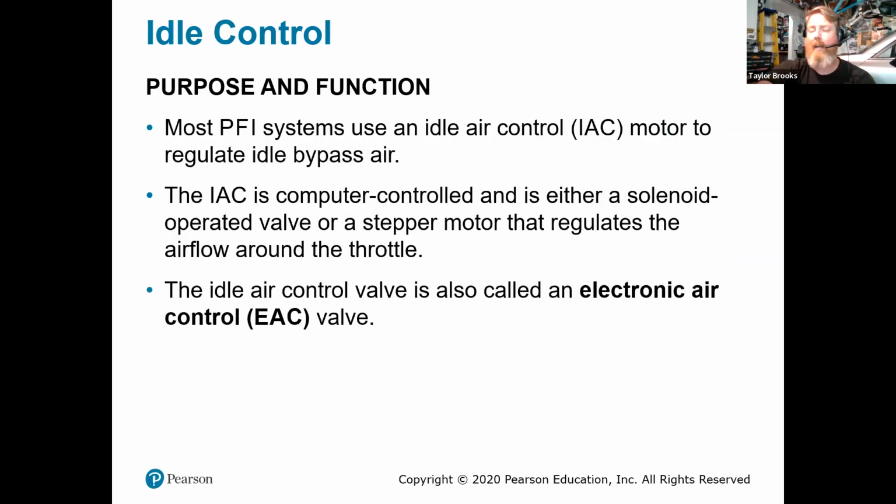When we're looking at how this is operated, typically the PCM or engine control unit is going to be controlling a stepper motor that is going to be actuated based off of the engine temperature and load. Obviously, we don't have to have the idle control bypass valve when the engine is accelerating, so it shuts off at that point. So we're only using it at idle. And you will use the idle air control when we are at operating temperature as well, because it is allowing the engine to maintain a consistent idle at all times.